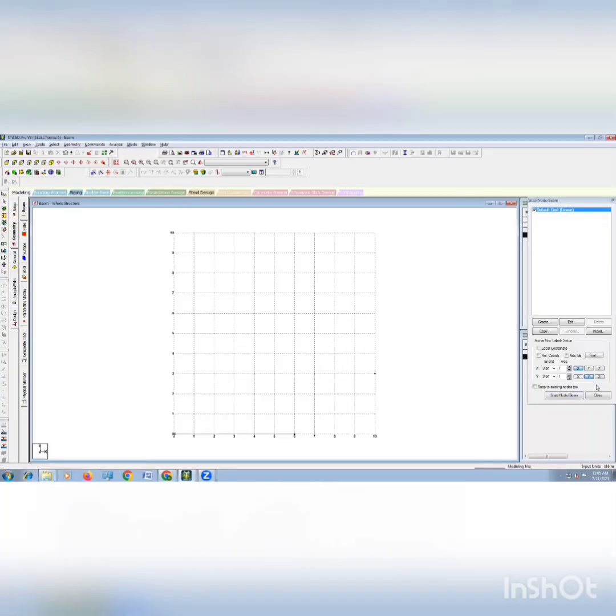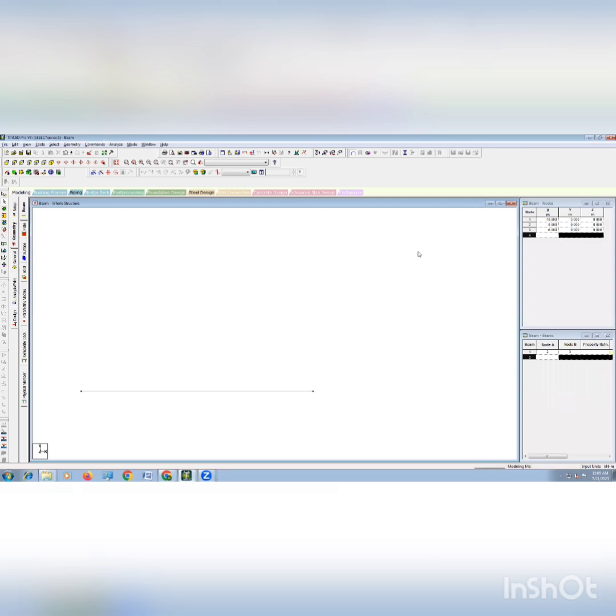After that, go to a normal plane. So close that dialog box. You will directly go into a normal plane with beams. After that, you have to assign the type of material to this beam. For that, go to commands. In that, select member property.